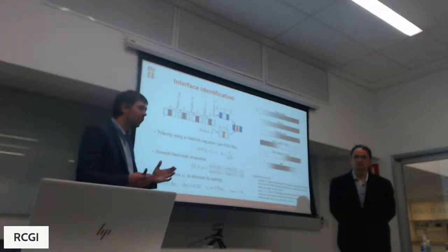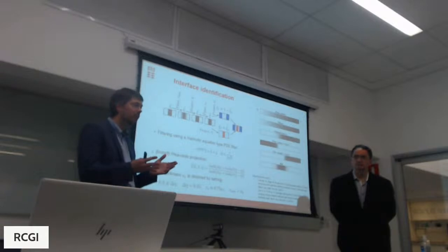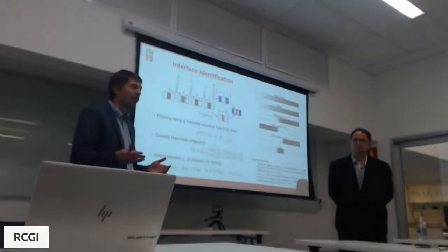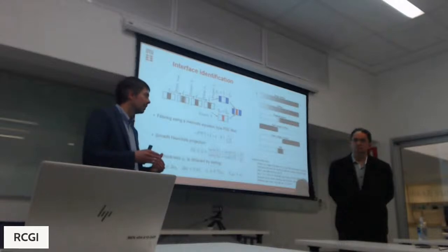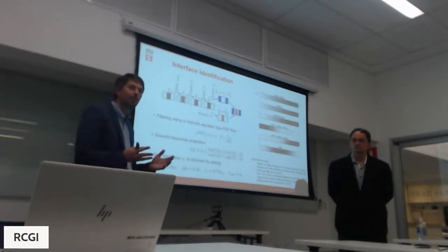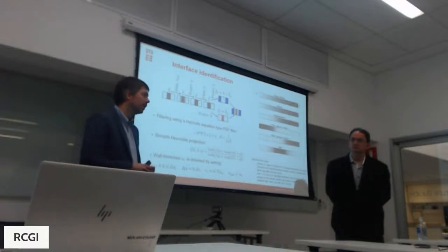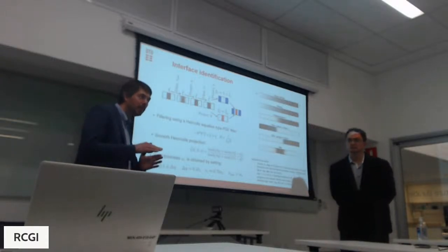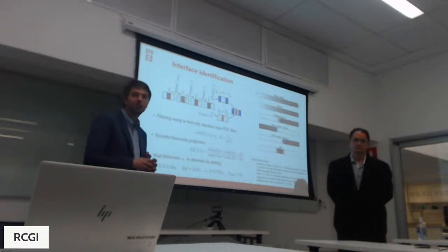But for instance, for heat transfer in heat sinks for computers, you're not interested in having turbulence, because then the flow and pressure drop relation changes to something that is not as advantageous as the linear relation between the flow and pump pressure. So they would actually like to keep it laminar if you can, but the effort of trying to keep it laminar in difficult geometries could be something.